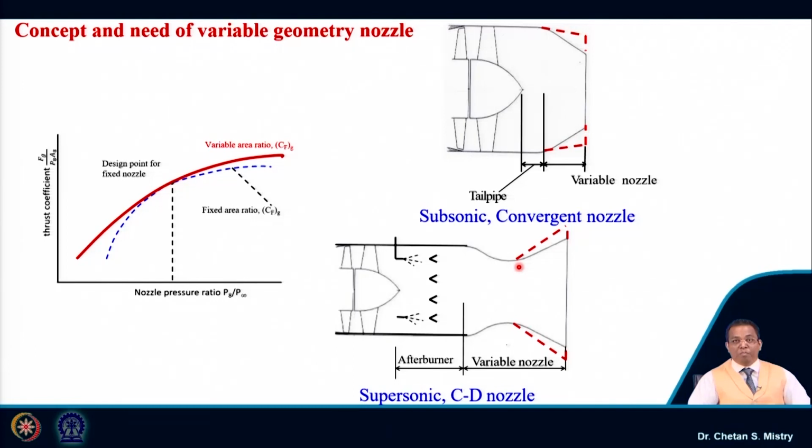So, we can vary both the throat area and the exit area. This kind of problem mainly happens when we incorporate the afterburner. We use the afterburner rarely, but whenever we use it, it demands a variable area nozzle. If we use a variable area nozzle, we will enhance our performance in terms of thrust coefficient.